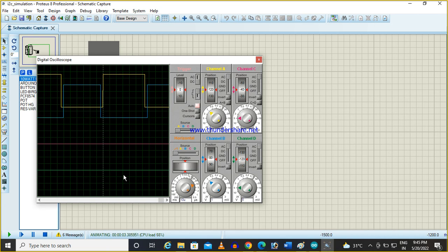So you can set your own dead time based on the data sheet of your IGBT or MOSFET, whatever it may be. But here it is a fixed duty cycle. In the next lecture, because we are going to make one sine wave inverter, I will explain how to generate the sine PWM.